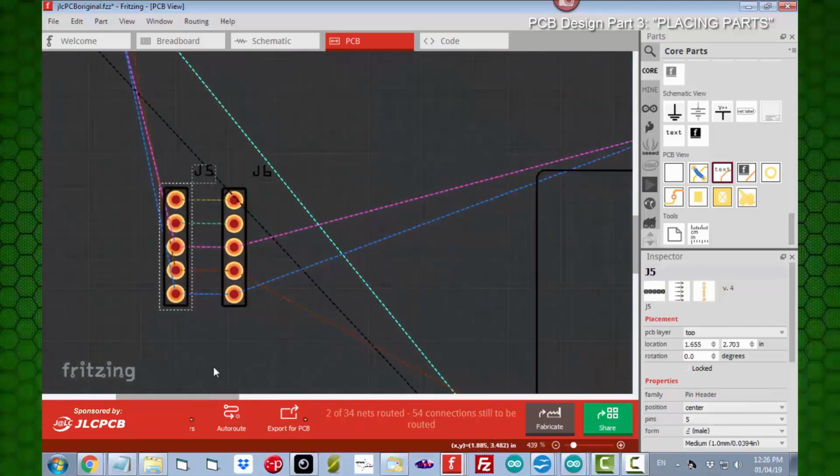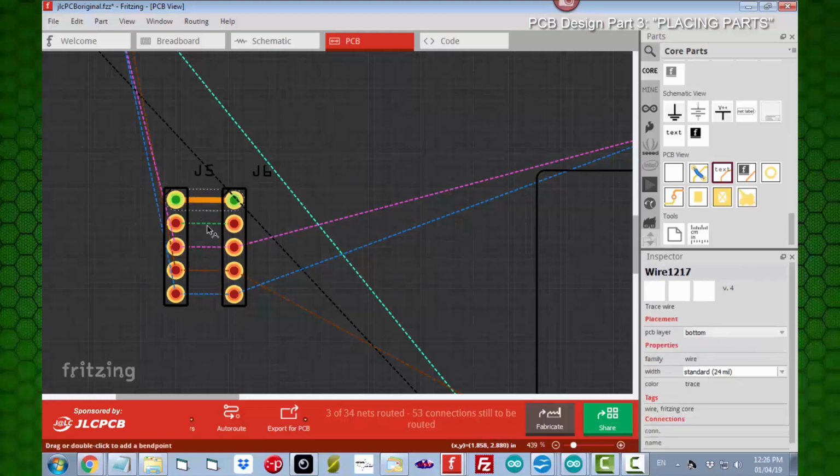These are the pins that go to the Arduino. And I want them on both sides of the board, and they will do the same thing. And so I'm just going to link these. If you notice, what I'm doing is I'm simply double-clicking those traces, and it puts these traces on there. That's actual copper. It's putting them on the back side of the board. We'll be able to rotate them around and do them later.